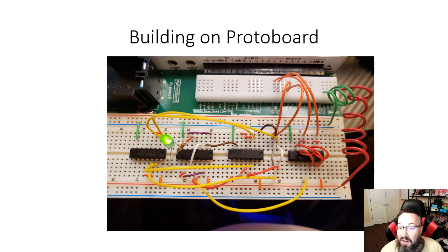As you can see, it becomes a little bit of a convoluted mess just due to having to tie everything together and then additionally jumper down to tie the inverters for the exclusive OR gate inputs back into the exclusive OR gates, which the color coding of the wires did help somewhat in keeping track of what was what, but there were many times when I had to pause to think about and write up what is going where and what is the ultimate function that I'm having this chip perform, be it the OR functions or is it building into the exclusive OR functions.